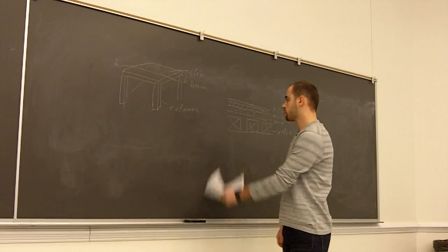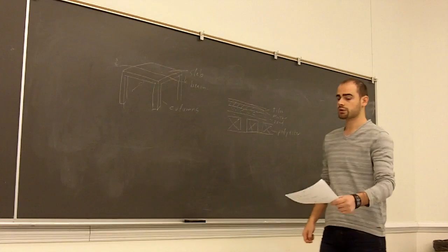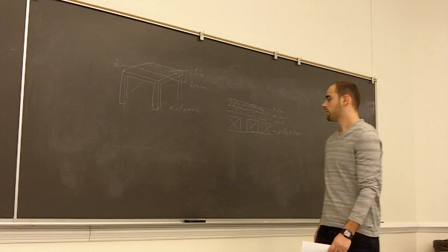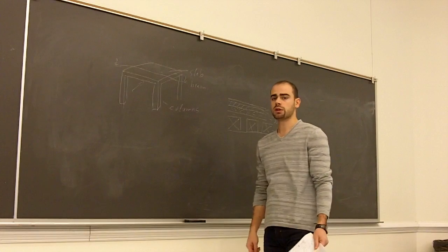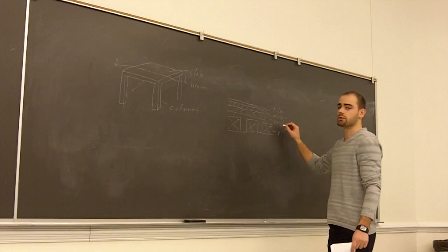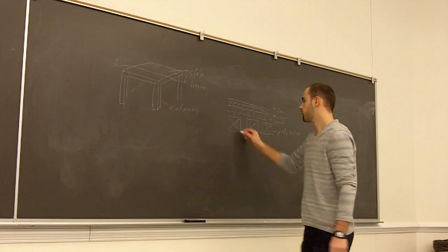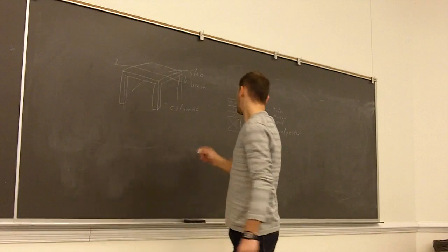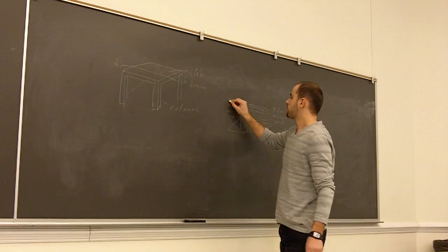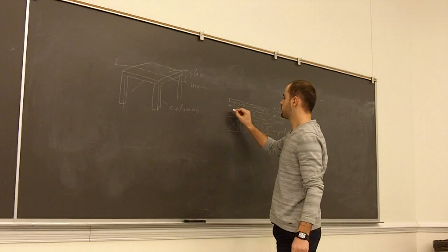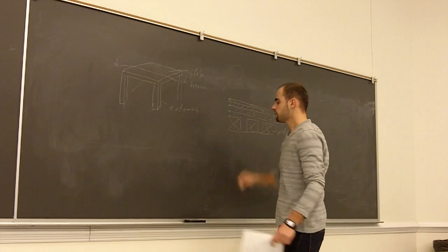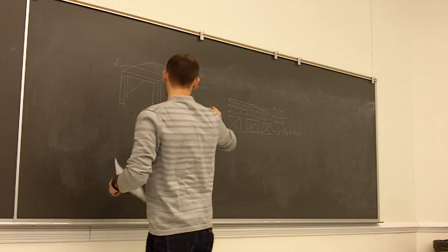To calculate the load of the slab, we have to calculate two loads, the dead load and the live load. The dead load is a permanent load, and these are the tile, the mortar, the sand, and the bricks and the concrete. To calculate these, we have to calculate all the thicknesses of these elements, and then we multiply these.